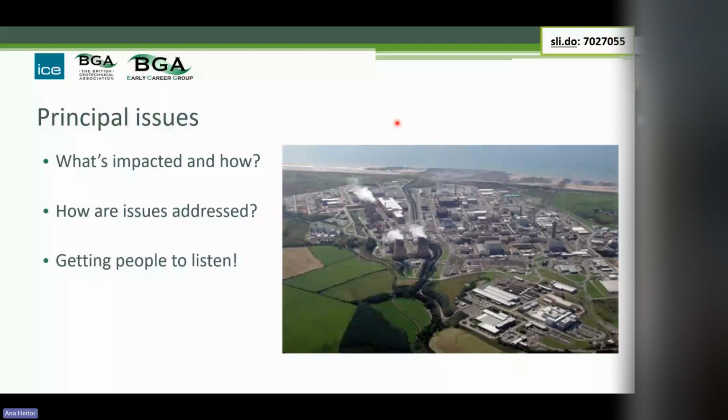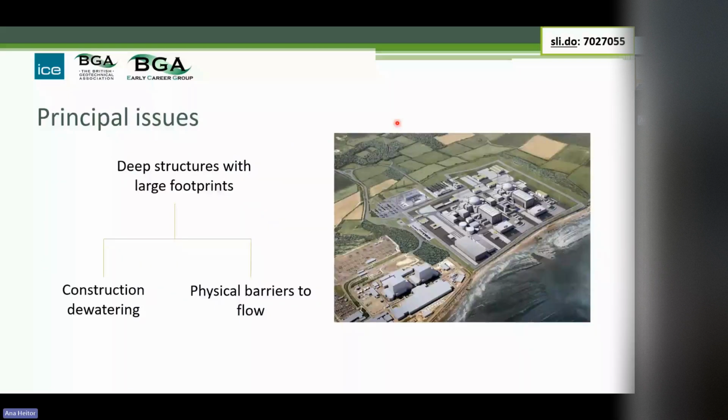In terms of what you're telling folk about, we're considering big structures, large footprints, large surface area, going down to depths. You're going to have to manage water during the building of infrastructure projects or development or energy infrastructure. As well as that, you're also going to have to consider the long-term effects. If you've got water present when you're building a thing, you need to manage it, keep it out of your excavation, and physically remove it. And Martin will come on to cover a lot of this in more detail in due course.